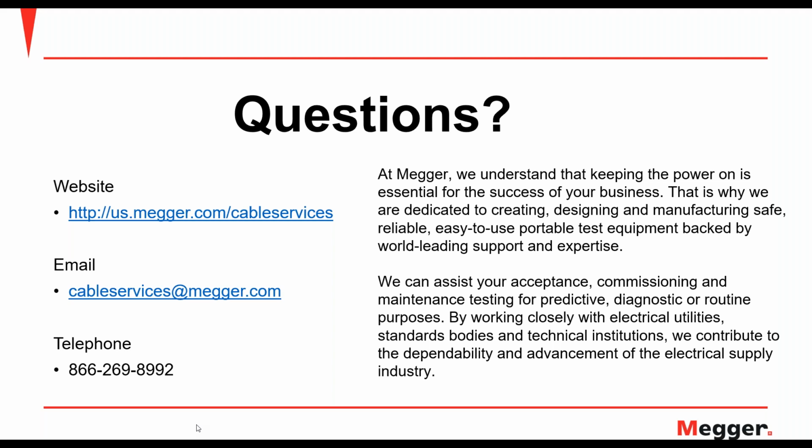Yes and no. So tan delta is a very important measurement. It's very vital. It's an integral measurement. It gives you the overall condition assessment of that installation. Now, what I want to highlight here is that this is one of the best things that you can trend, right? Because every time you trend that, you see whether or not the overall insulation is deteriorating, the overall condition of your insulation.